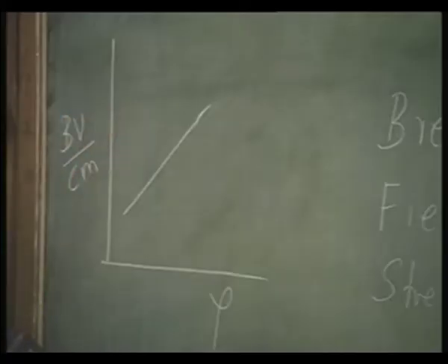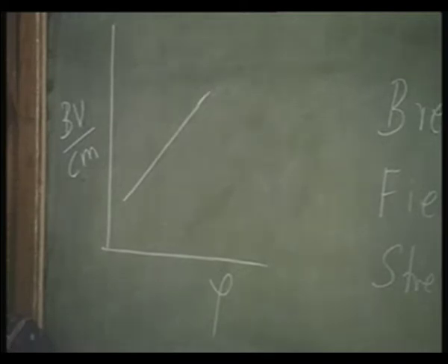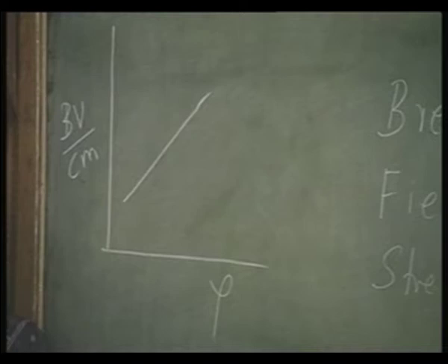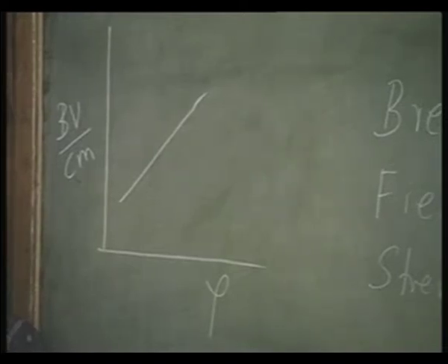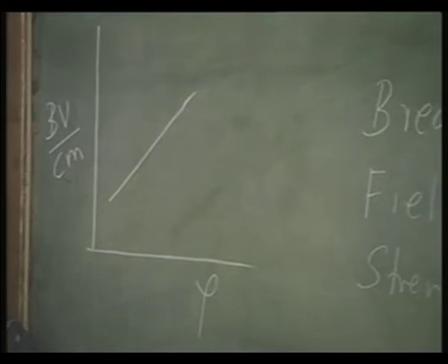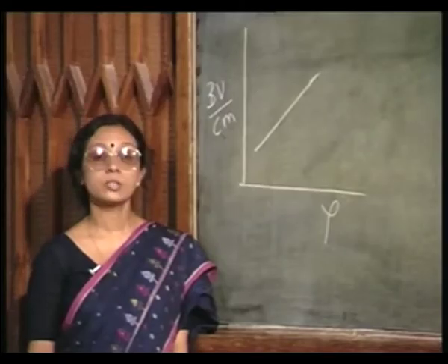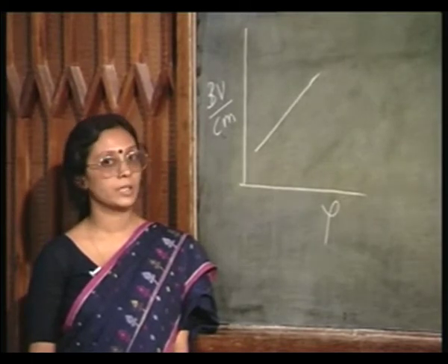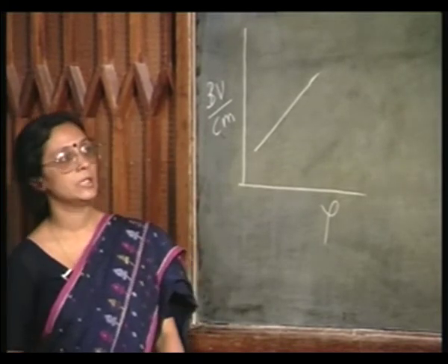So, since dry thermal oxidation gives the most dense oxide, one gets the highest breakdown field strength using the dry oxide. So, this is what we mean when we say that dry oxide quality is much better. This is one of the things we mean.